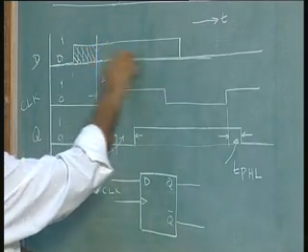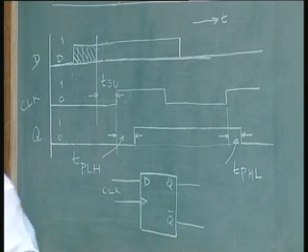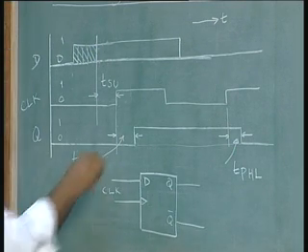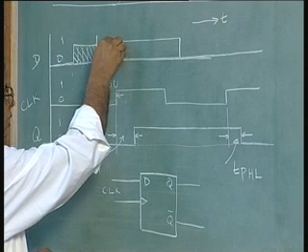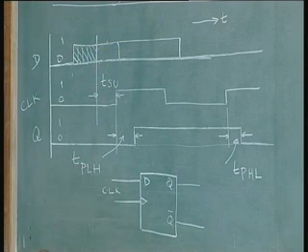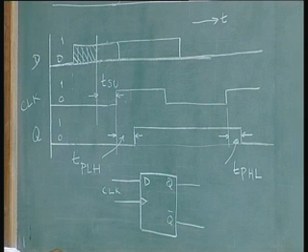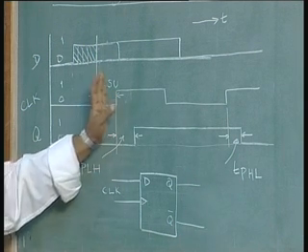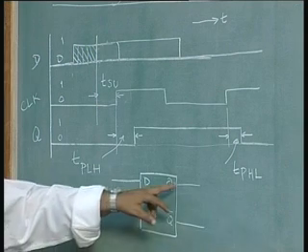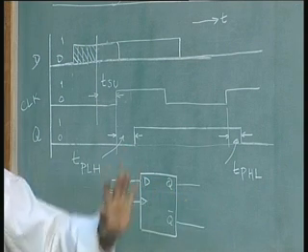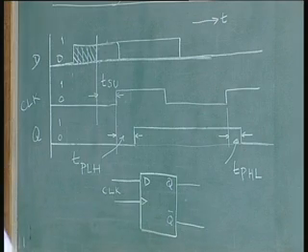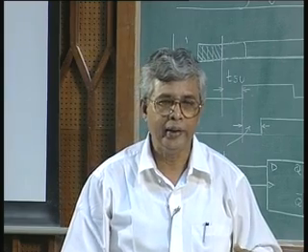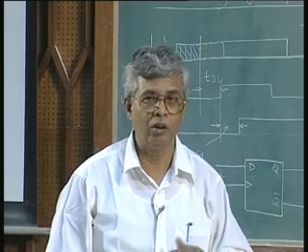Of course, in this case the D lasts so long, such a long duration. But if I say, is it all right if I remove D as soon as the clock transition occurs somewhere here? Again, is it acceptable? Now, there again there is a definition, there is a timing involved. There is a minimum time for which the output should be stable after the clock transition occurs for the output to be guaranteed again. This is all for guaranteed outputs, something like a quality. If you do not do it, nothing is going to happen, the world is not going to fall apart.